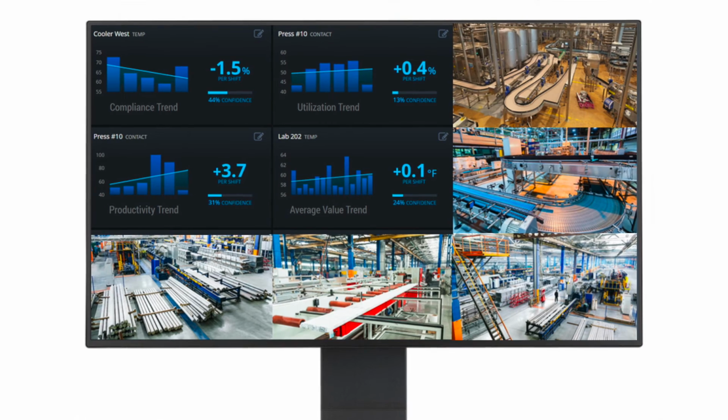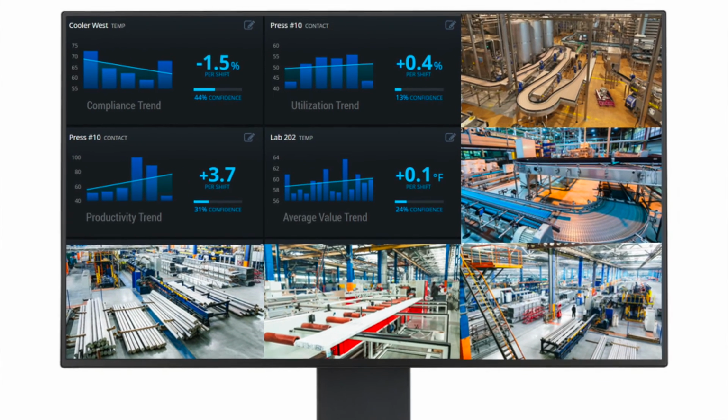Another one I can think of right off the top of my head is production monitoring, which is a lot of where decoders are vital, and you have to have them because you're monitoring a lot of cameras. You need to see a lot of them statically, but you might also need diagnostic or performance info being sent from a computer or some other device, and you can plug it into the HDMI input on the decoder, and then display it as part of those grids. So you always know that your diagnostic info is here while the cameras are surrounding it, and that way you're just utilizing the space, because that is a concern with any kind of thing.